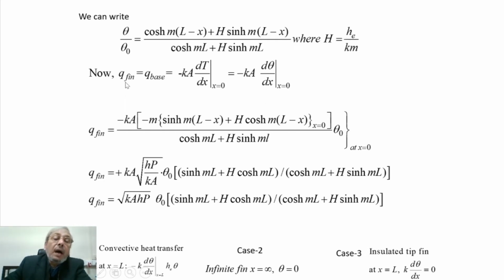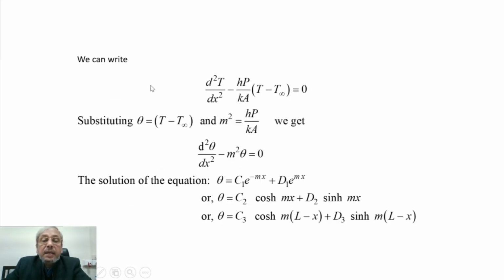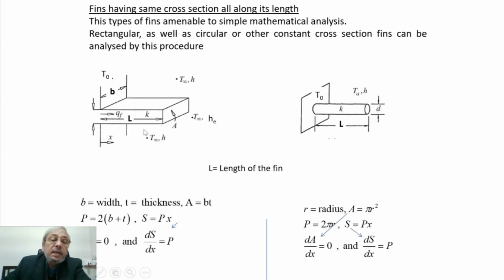Now the heat transfer through the fin is basically, the fin is cooling. So the mechanism I can just once again highlight. The surface will be cooled by the local fluid, local ambience, and that will promote heat transfer, that will bring down the temperature, and from the base energy will flow through the fin.